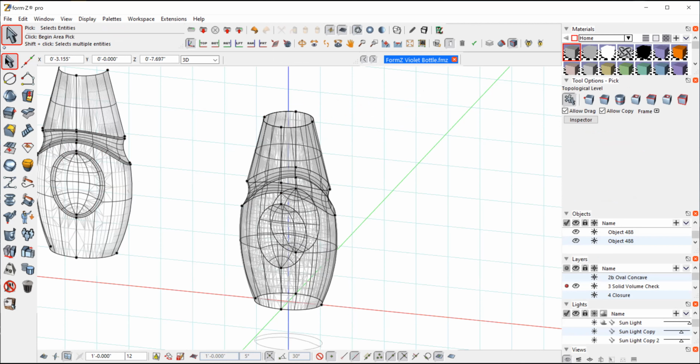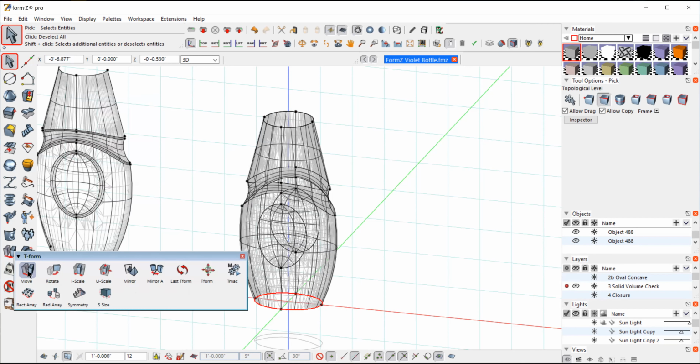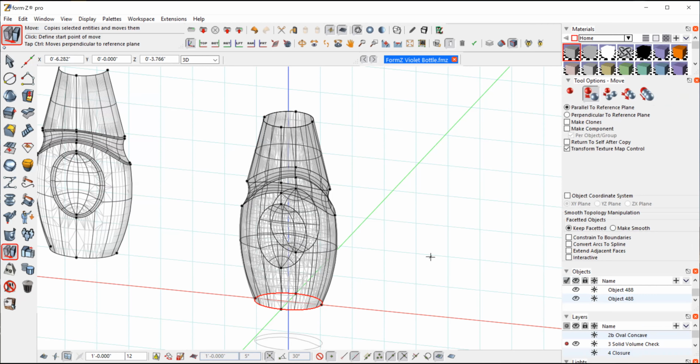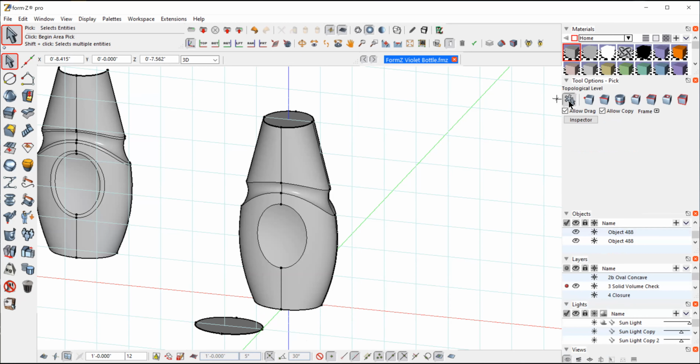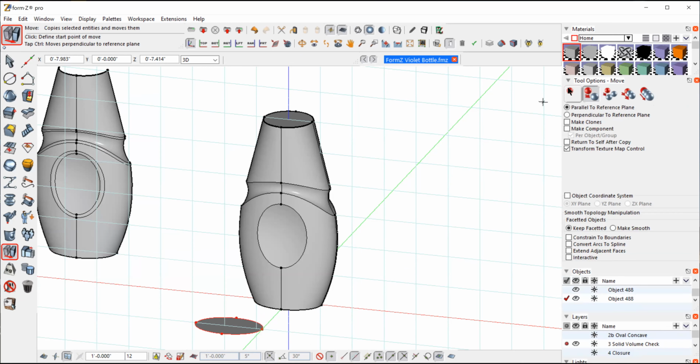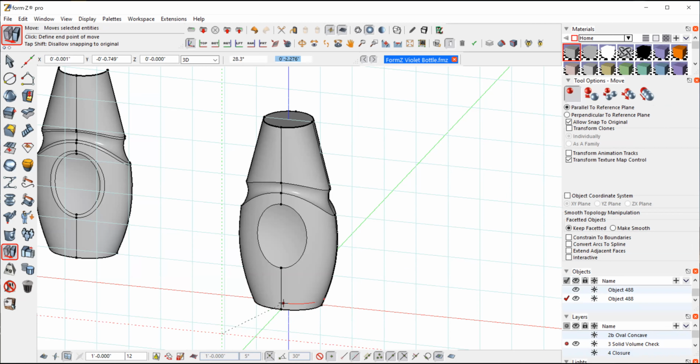So if I go into hidden line, I have to go segment. I can just lasso these. And there they are. Move one copy. And just to double check, if that's nice and gray, then that's perfect. I'm going to go back to object. Select this, not faces, not lines. And I'm going to move that, not a copy. I just want to put this back into position where it came from, but now I've created a surface.